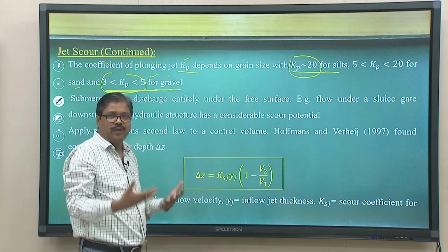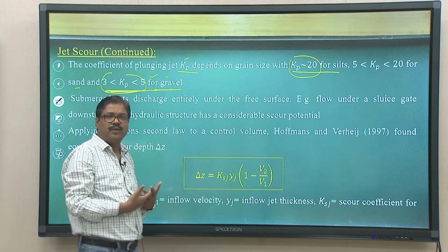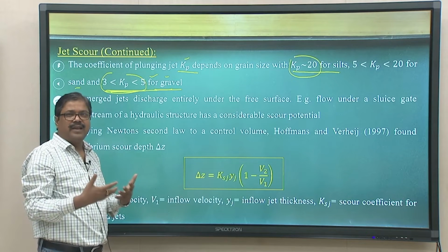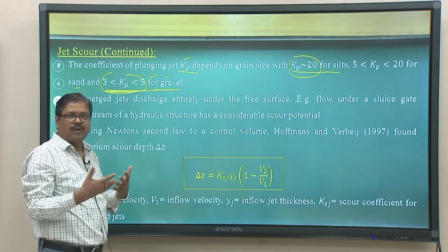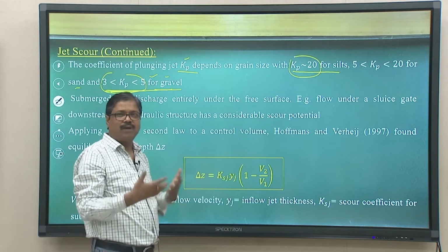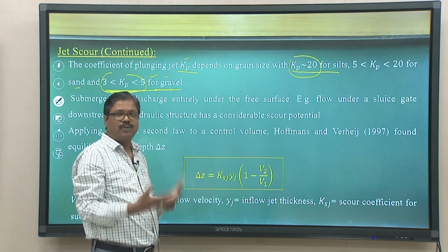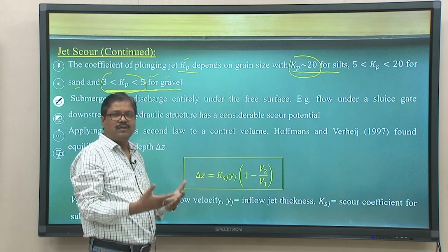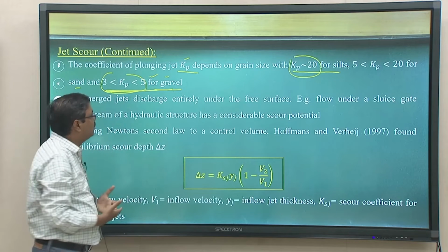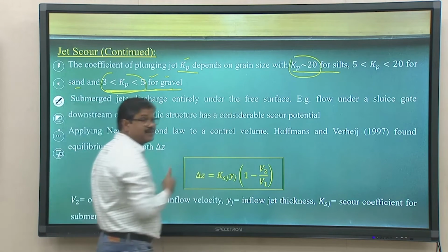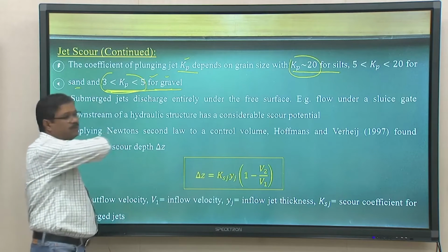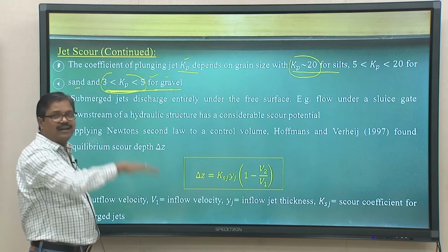So, we do not know what type of flood is going to come, and in that period how do we manage it, what could be our strategy to look at the safety of the dam and the weir structures, because we have to protect the scouring mechanisms, protect the scour holes. To protect the scour holes, we should have this knowledge of the scouring, that how we can manage it with the gravels or tailwater depth.